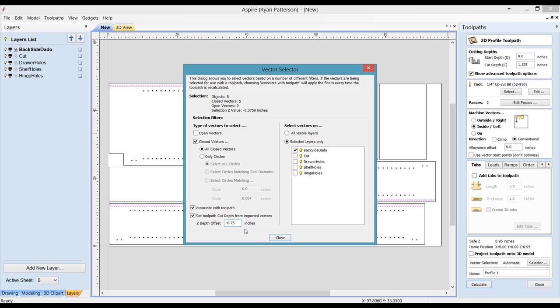But this toolpath template may be used later for 5/8 material, or 1/2 inch, or whatever material thickness. So we want this setting to be able to float with whatever material we enter in our job setup. So instead of leaving this as a number, I'm going to enter in minus T.